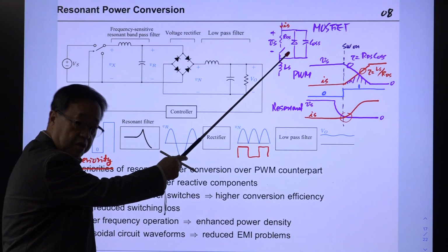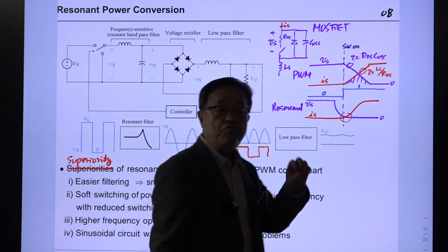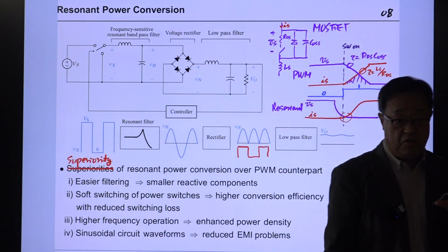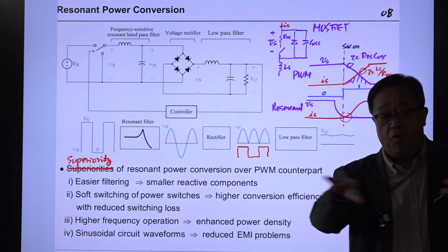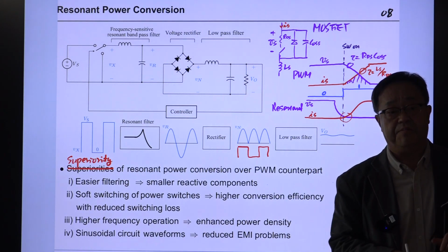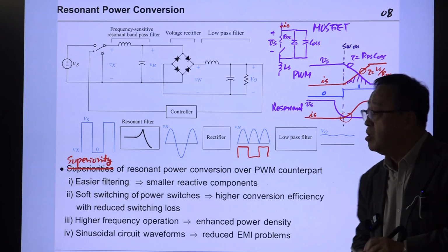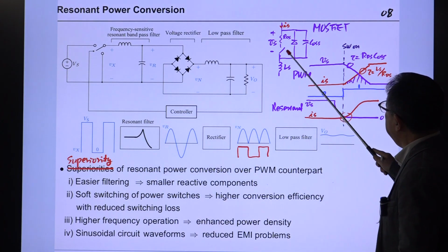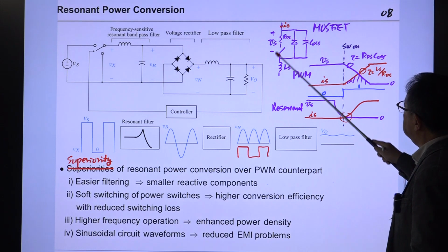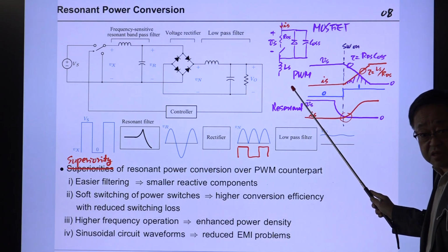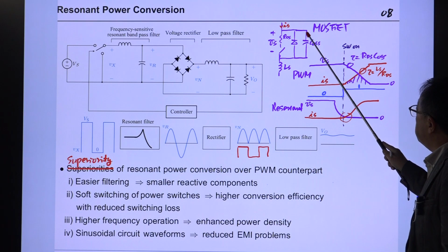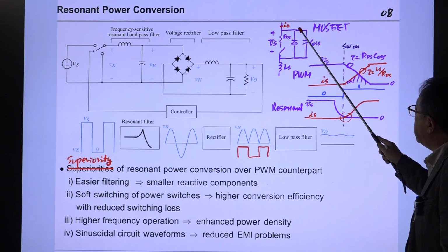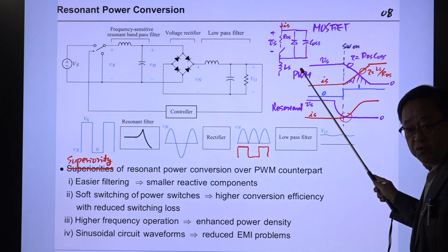It comes with the structure of the MOSFET. If you have a MOSFET, then you have a body diode. You cannot separate them or eliminate the body diode. It has some parasitic elements: this is channel resistance, this is parasitic inductance, and this is parasitic capacitance between gate and source terminal, COSS.